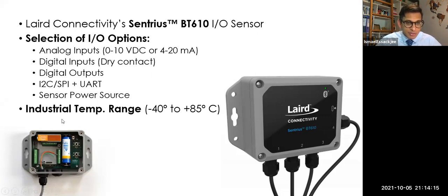Most important for us in this slide is the industrial temperature range. Where can we use that? Minus 40 degrees C up to 85 degrees C. If you're going to operate in an environment, maybe a special kitchen, a furnace, an industrial environment, going beyond 85 degrees C, you can't choose such a device. It's not a sensor. It's just going to pick up all the information and then send it somewhere else. If it is going to operate below minus 40 degrees, you will need to select another device.